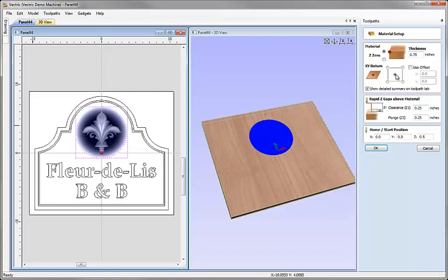In this case, we have it set to the middle of the job, and ordinarily there'd be no problem with that. Really, it's just personal preference as to whether you choose the middle or one of the corners as your XY0 position. For this particular example though, there is a reasonable argument why setting it to the center would not be a good idea.